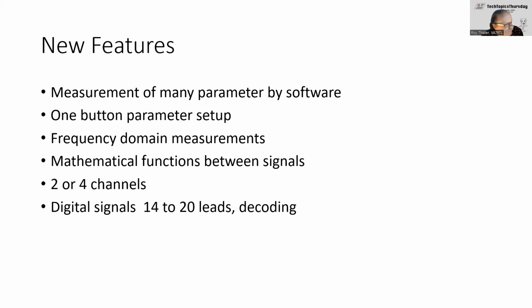So you'll find some of the analog scopes at the swap meets now, and some of them may give them away for free, but you might only be able to get up to like 1 megahertz or 10 megahertz. So that's something you need to look at. And also again, what are you going to use your scope for? If you're looking at basic electronics and playing with different circuits, maybe 1 megahertz or 5 megahertz may be enough for you.